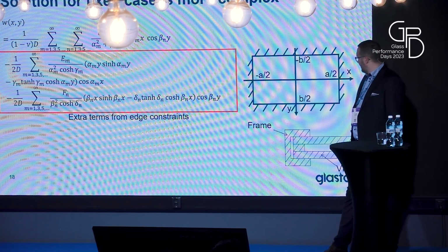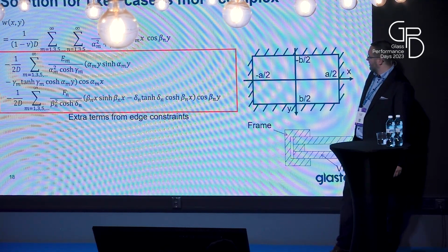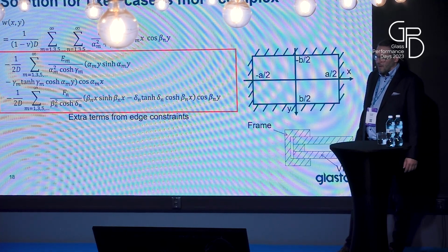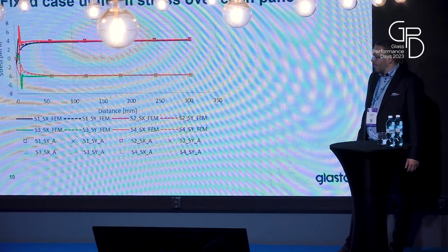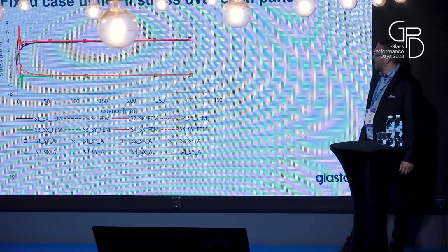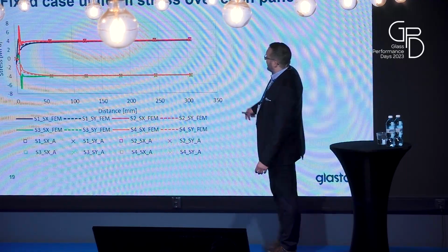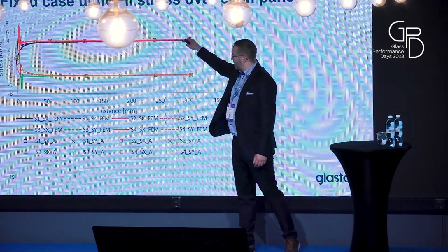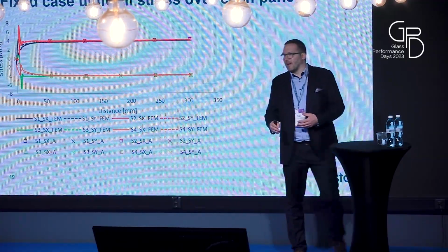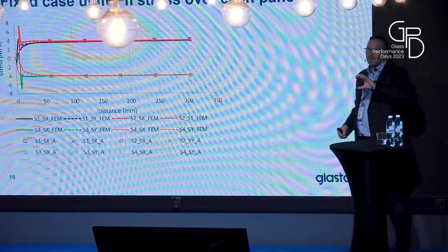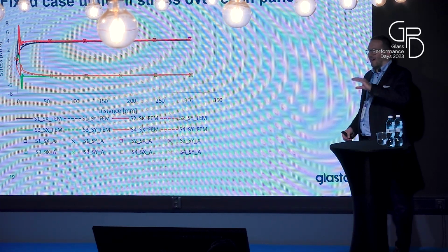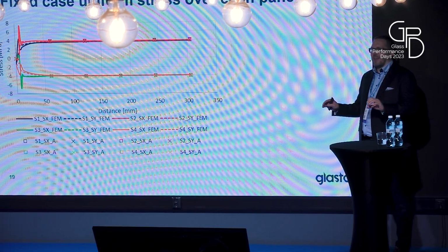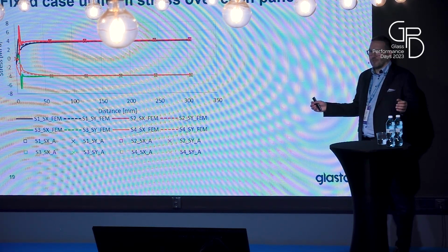Say, if something is bending from that pane. And if we are looking at results now, you see that top ones are on surface 1 and 2, so that's a coated pane, and stresses on both side surfaces of that coated pane are the same. So that means that there is not really bending, it's just a flat case, and all the stresses are coming because of temperature change.